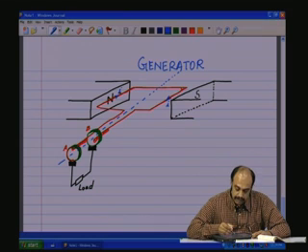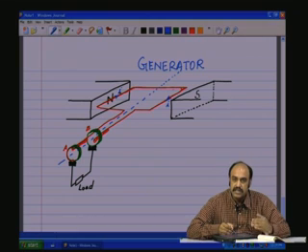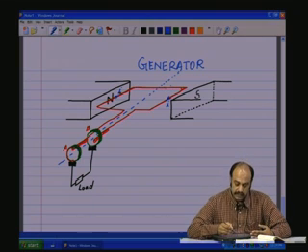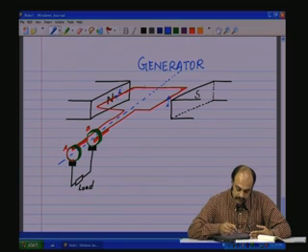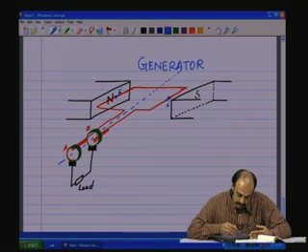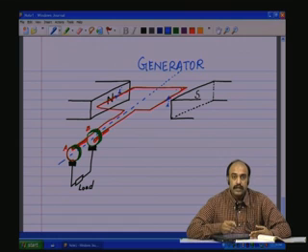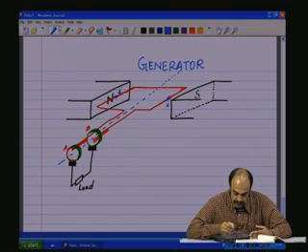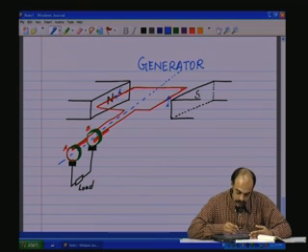Now, this portion is in a perpendicular direction, along the field. This portion of the conductor does not cut the field, does not see any differential flux amplitudes throughout its rotation, and therefore there is not going to be any induced EMF on this line and this line. So, these two are going to have currents induced, one in this direction, one in that direction, and this is fortunate for us because we have drawn the coil such that current can flow like that through this coil, flows through this coil and comes out through this.